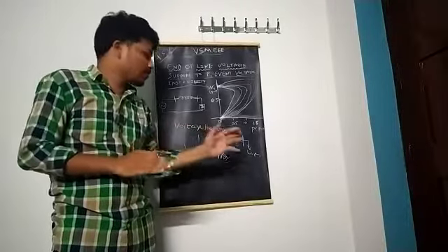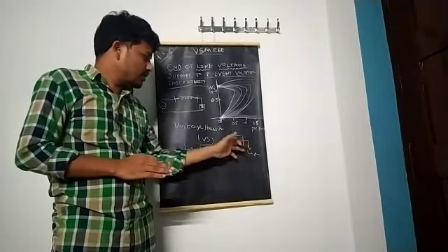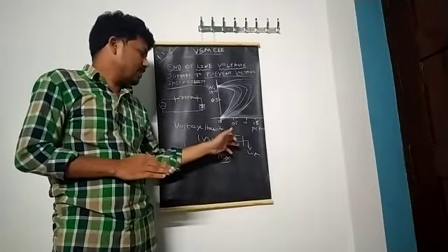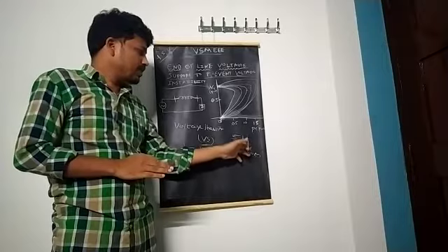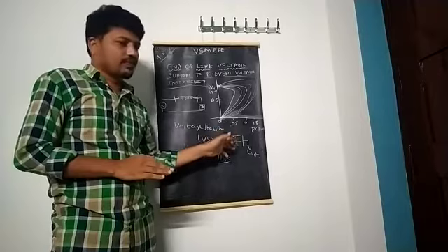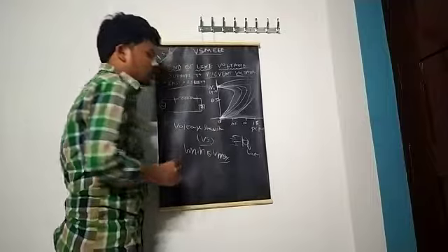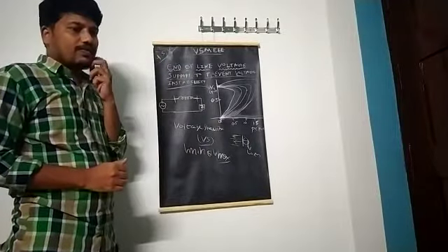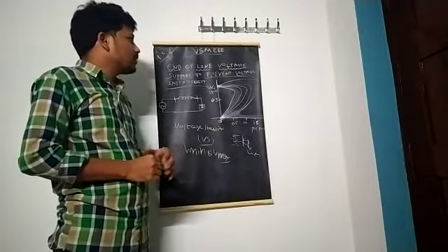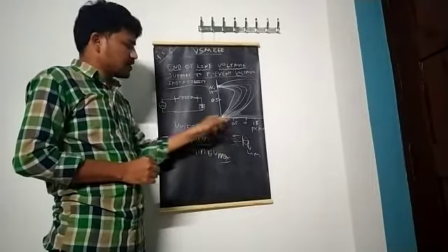Therefore, generator 2 is disconnected from this load. That means the entire power will be delivered from generator 1 to the load. Generator 2 in this situation will not carry any power. Therefore, the entire power is borne by generator 1. Due to this, a voltage instability problem occurs at the load end, that means the receiving end. There may be overload or underload situations. So this kind of situation is a voltage instability issue due to the loss of one generator.